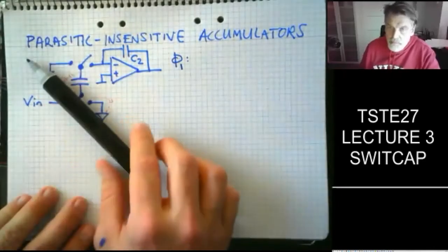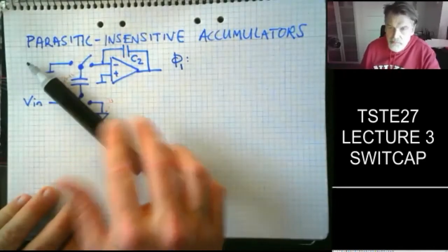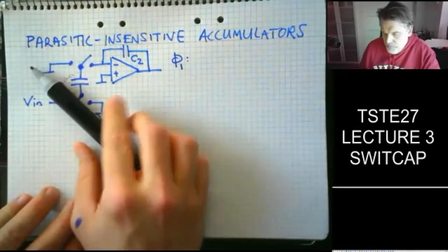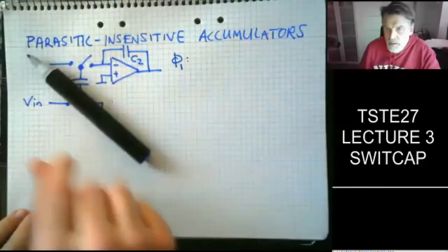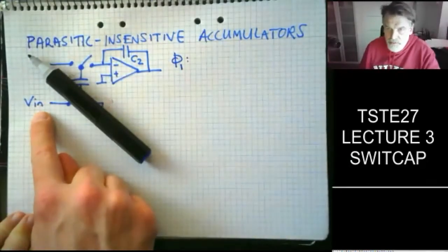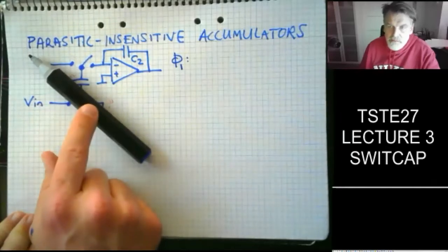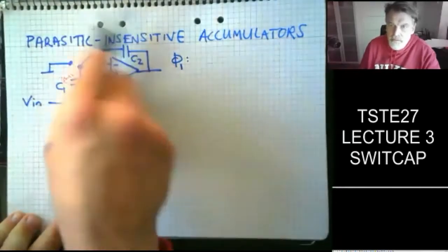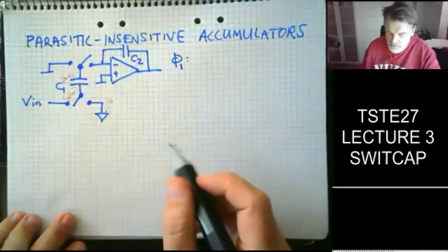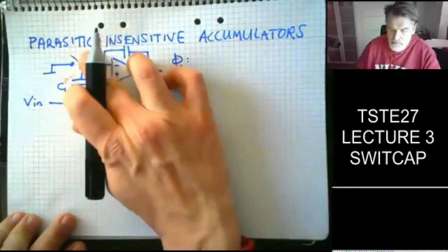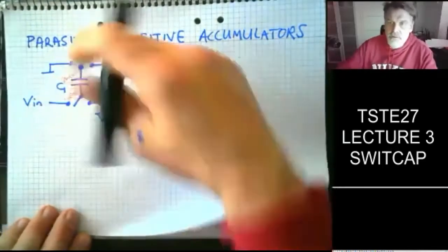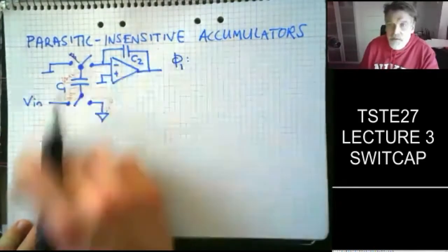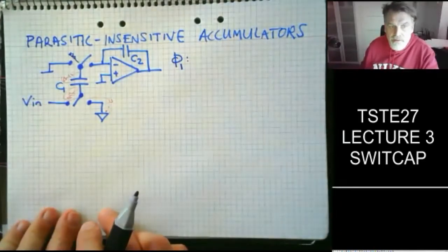Notice that we could flip one of the switches here. That will actually change the transfer function. We will see that shortly. But what happens is that we get a delay of the input signal by 180 degrees. So I can choose the delay of my circuit by setting these switches in different starting conditions. I could also move this and have that as a starting position, and that would also give me 180 degrees phase shift. So it's quite an intelligent block in that sense, in its simplicity.